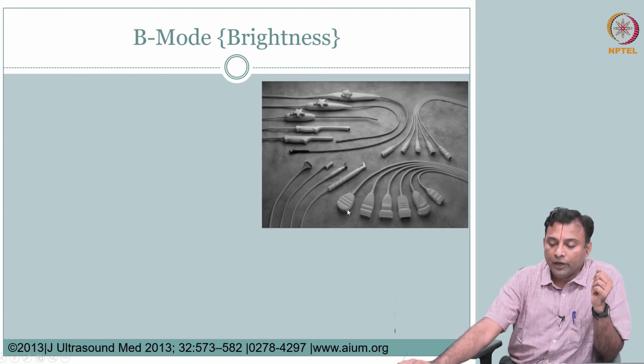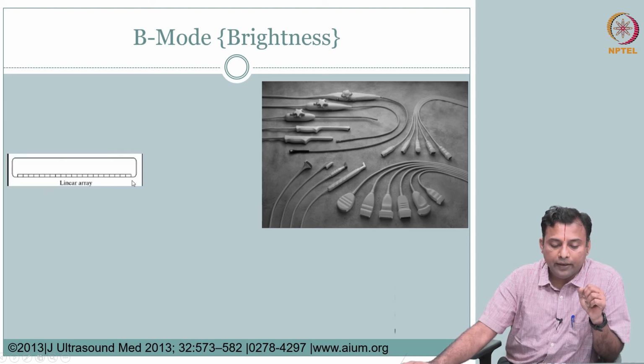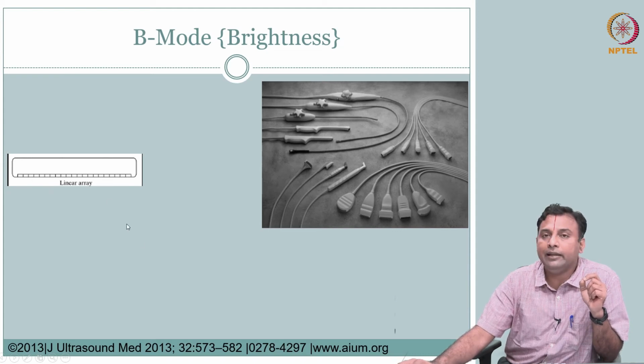Okay. Predominantly, what we will cover in this course is the underlying concept of how an array is used to form an image. So, we will not go into detailed application-specific transducers. We will cover the generic ones, for example, the linear array, where elements are positioned next to each other along a line. These are different elements, independent piezoelectric crystals placed next to each other in a linear array form. This is called a phased array.